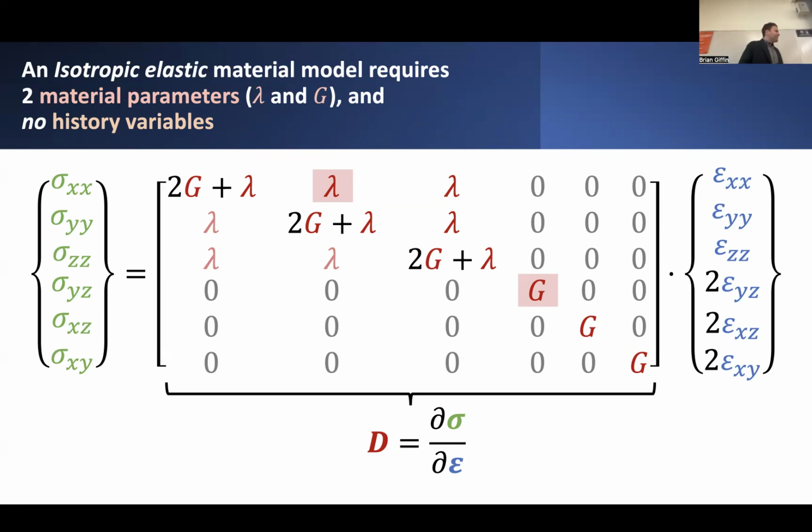Now, it's fairly straightforward to see that if we wanted to determine what's the tangent modulus of this particular material model, then it turns out that regardless of how we've chosen to define our incoming strain increment, the resulting tangent modulus is the same. Or in other words, it's basically exactly this 6x6 matrix. So if we needed to use that to assemble our stiffness matrix for the element, that's the exact kind of expression that we would use.